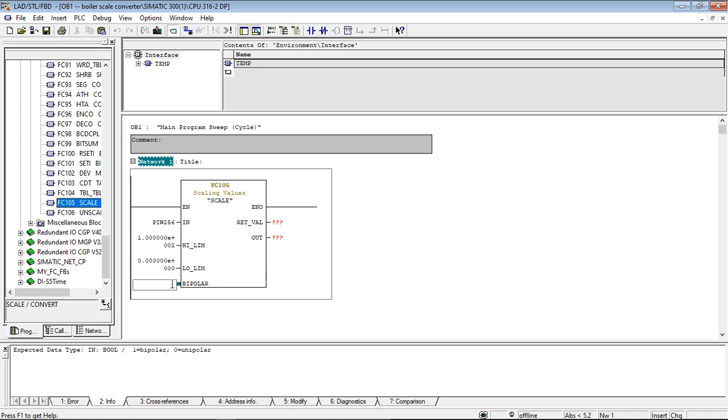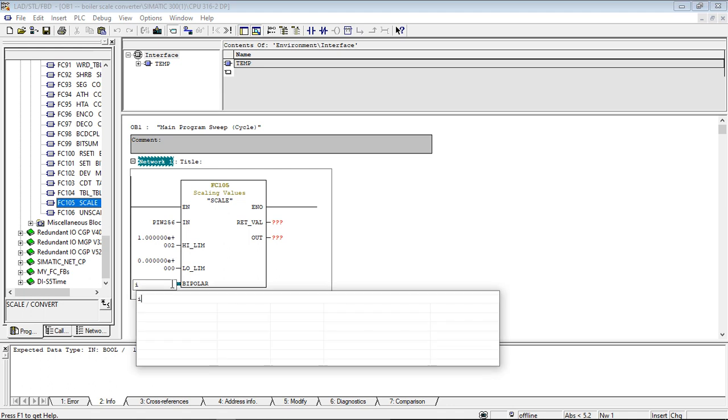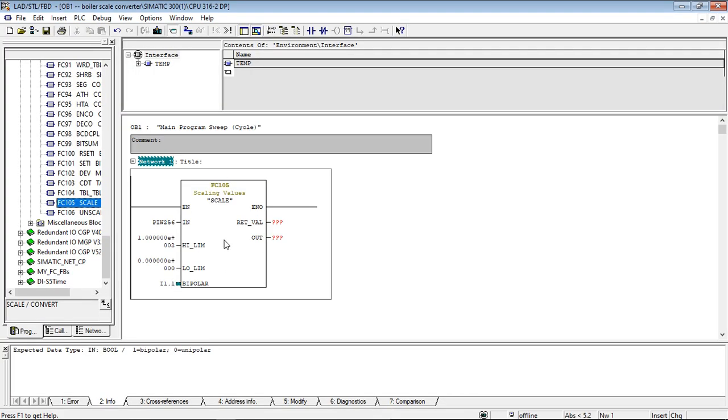Here you can put a memory, or an input, or a switch or a button. I1, that's an address on my own module, I1.1, let me use that. So your return value is, if this conversion encounters an error, where it will be saved, and that is a word.